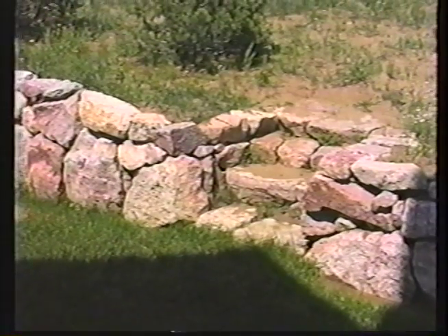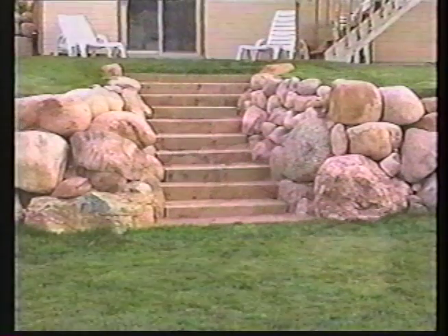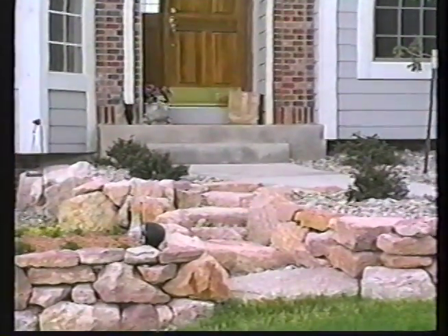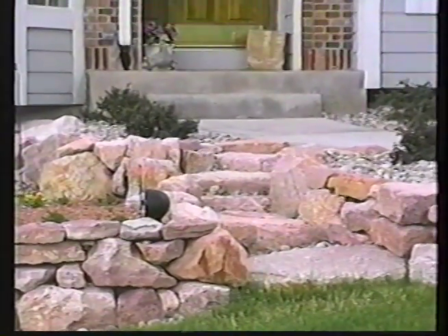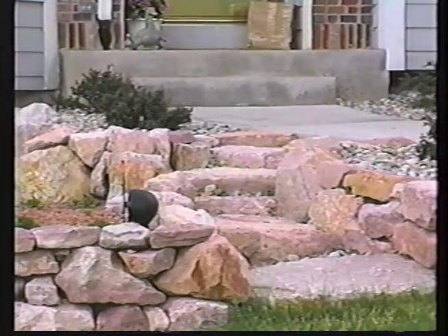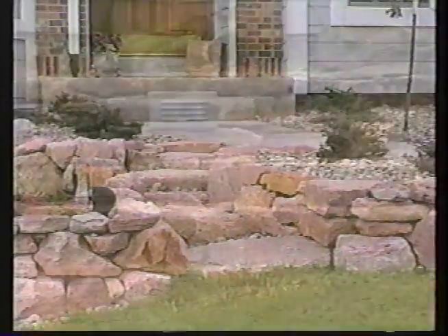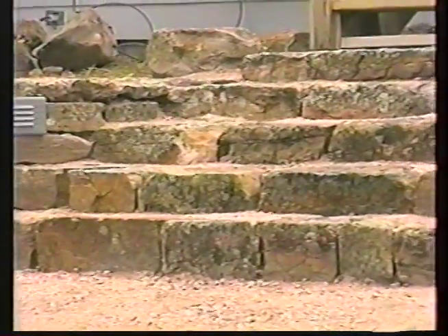Your wall will need to turn into the hill and begin to overlap the end stones making up the treads and risers. Another option is to use timbers for steps through boulder walls. This shows it more clearly. All soil beneath each of the stairway stones must be compacted, and all backfill must be firmly compacted as you go. You will see that different looks can be obtained by using different techniques.